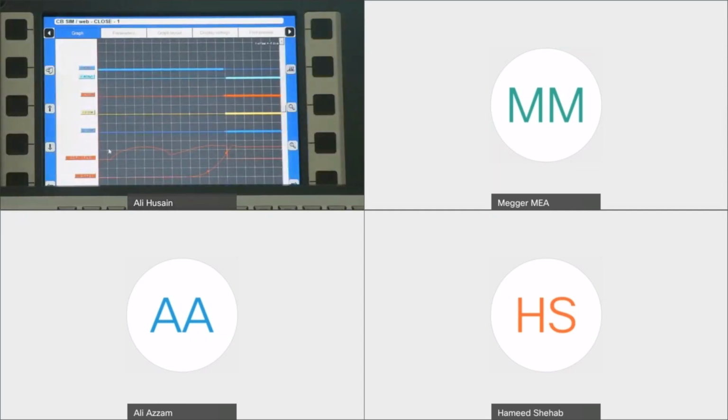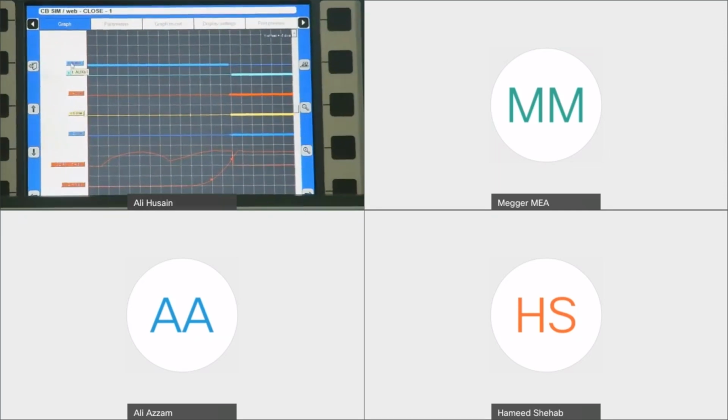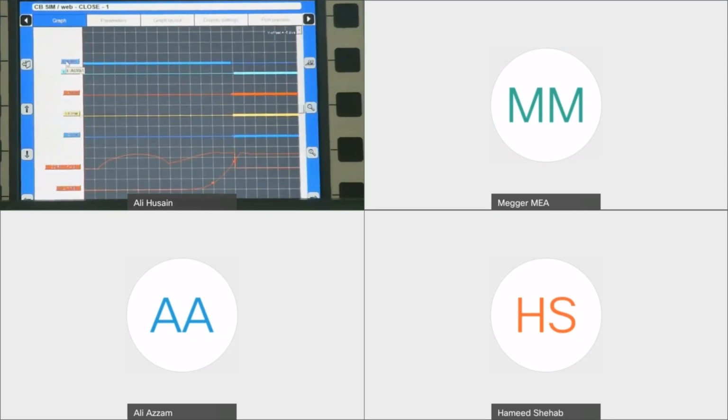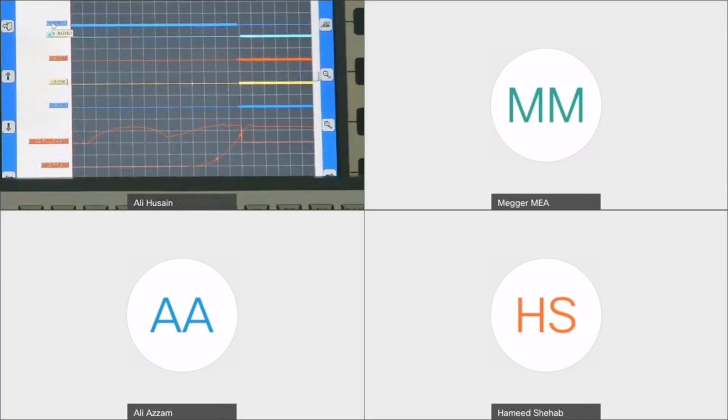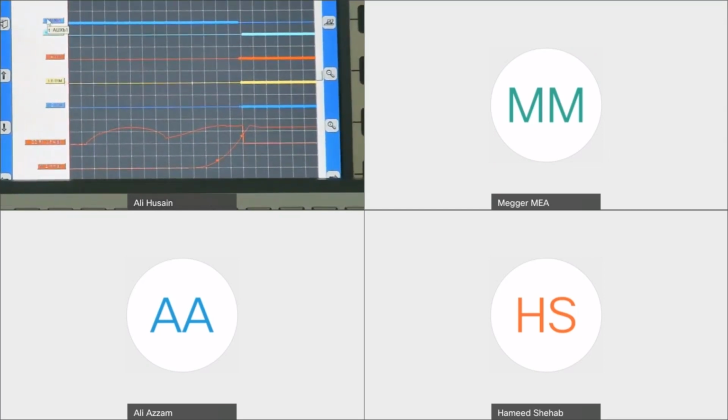As you can see, the result is showing here now. From the result, I can see I have some auxiliary contacts. Let me zoom in more. So what you can see here is the auxiliary contacts values. I have the main contacts, phase red, phase yellow, phase blue, and I have my coil current, which we'll talk about later on. And last here, I have my motion measurement.